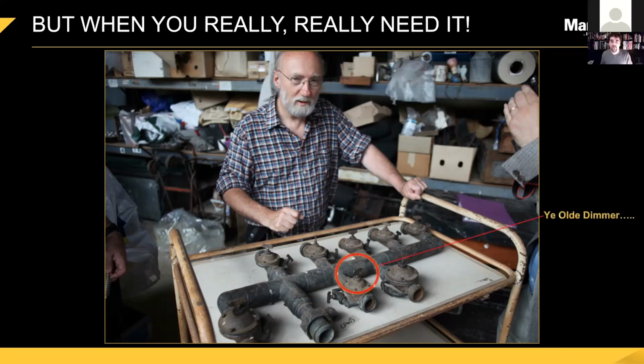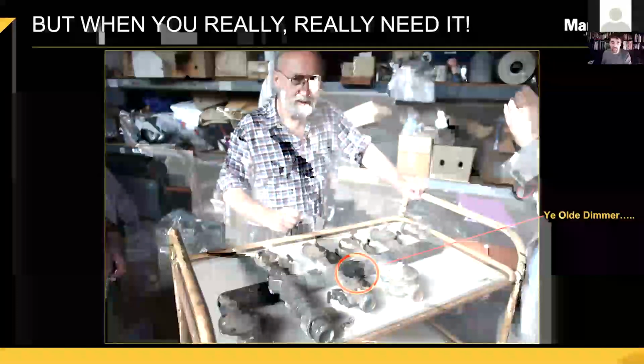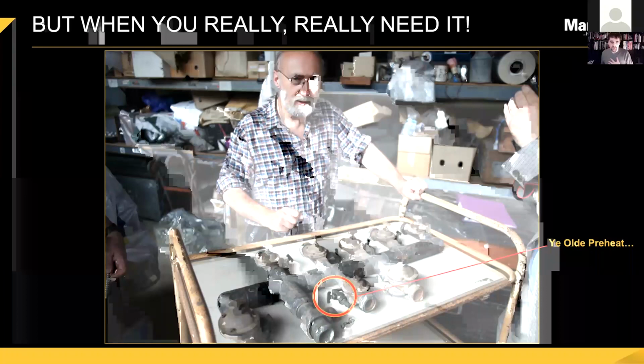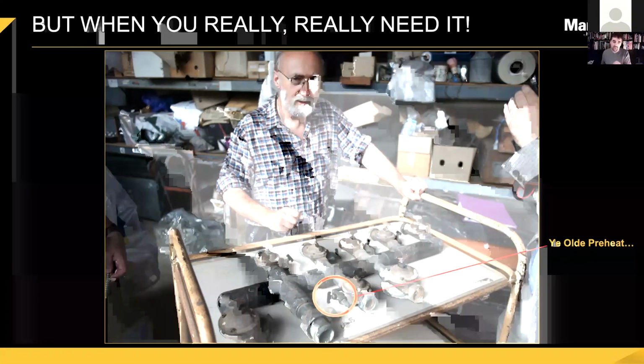So you need a way of making sure that doesn't happen. So if we do that, that's the dimmer. That's how you fade the light up and down. But if you look on the side of each of those pipes, there's another little tiny one, which I'm calling the preheat, or bottom set. It's a little tap that would let a little tiny bit of gas bypass the dimmer, so that even when you turn the dimmer off, there was still a little bit of gas getting to the flame, and you would have a little tiny flame, but it hadn't quite gone out. And you could adjust that for the different flames and the different lengths of pipe, just to make sure that when you faded everything to zero, the light didn't quite go out.